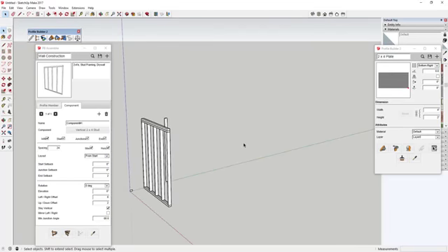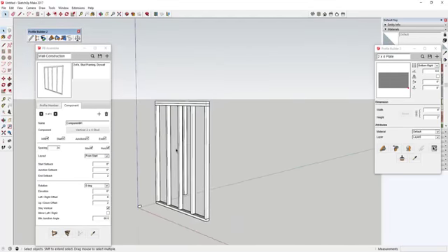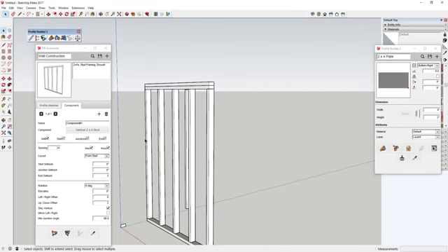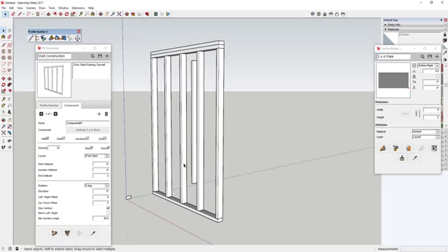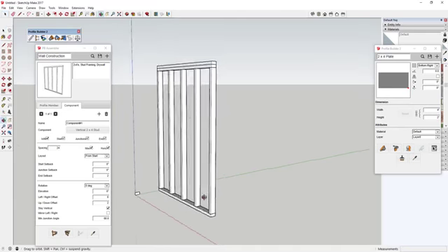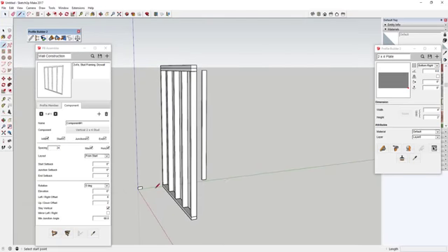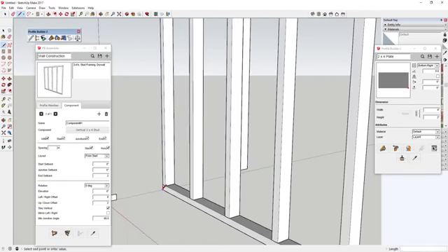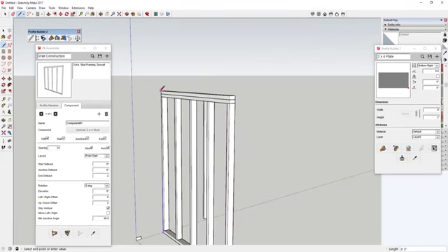So the next thing we're going to want to do is add some 3/4 inch sheathing to one side of the wall. Basically, both the sheathing and the drywall are going to be profiles on here, because again, you want that to extrude all the way along the length of this face. So all you're going to do is come in here and draw, probably right here for right now, a profile for plywood. You're just going to draw a rectangle. We'll call it 5/8 inch thick.